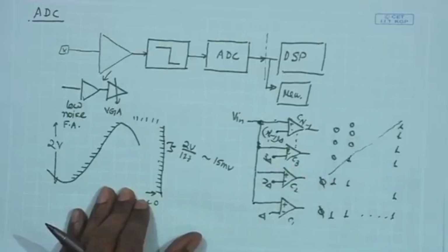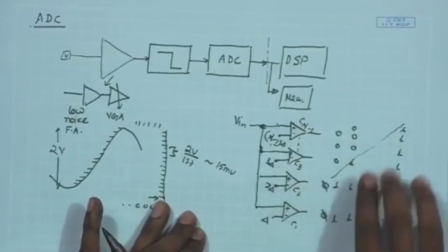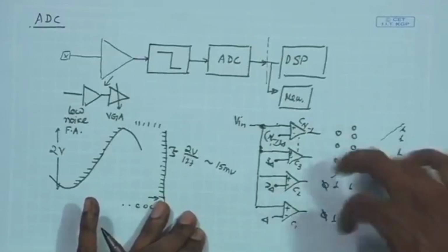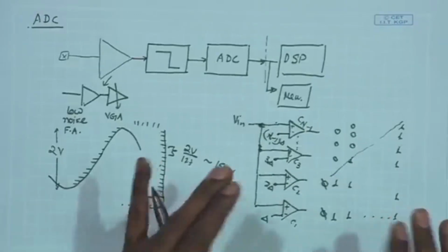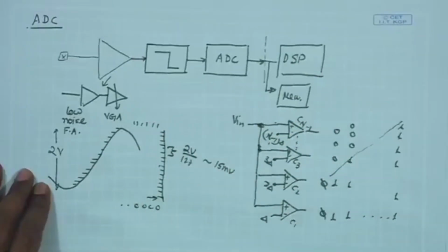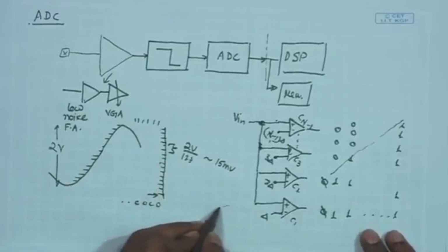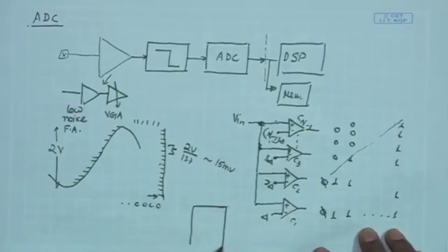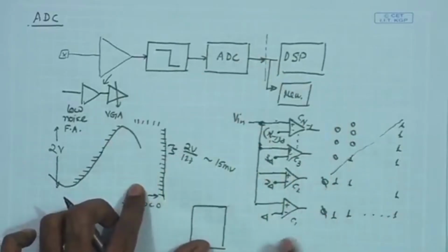high is increasing. And of course, this is not the binary code, this is a thermometer code, and therefore, from here we need an encoder which can convert this into our binary code, 7-bit binary code, and for that we need to just look at the corresponding truth table and arrive at the digital logic. So, rather than going into detail, we can just say that there is going to be an encoder which is basically taking in these n minus 1 inputs.